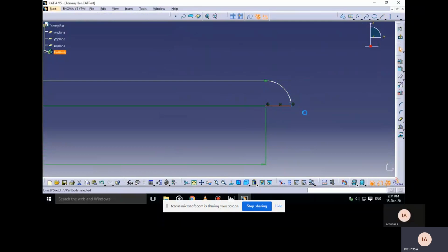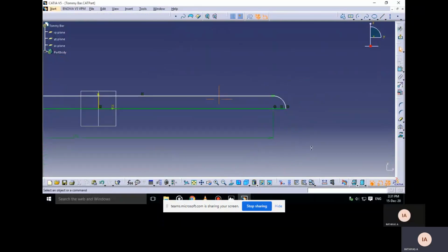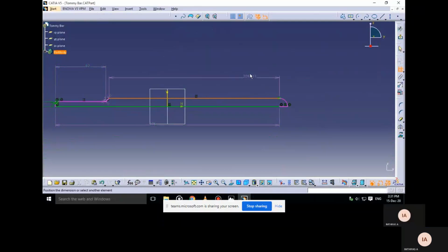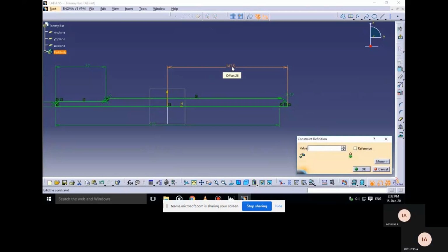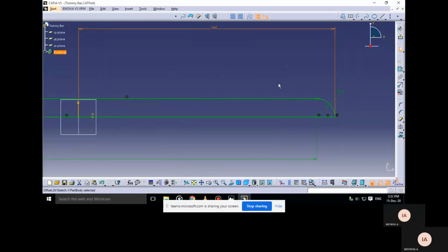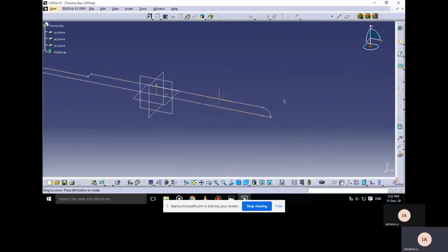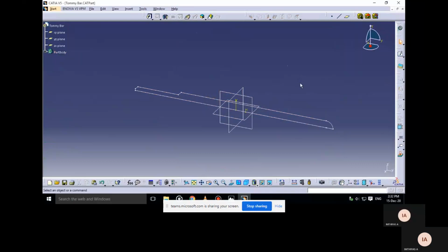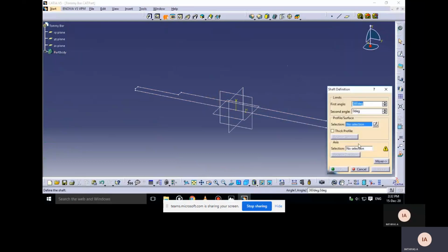As only half the part has been made, we are connecting it with a semicircle. Using the shaft command, once it has been revolved, the total diameter of 20 will be made. Now the radius is 10. So now we will revolve it using the shaft command.